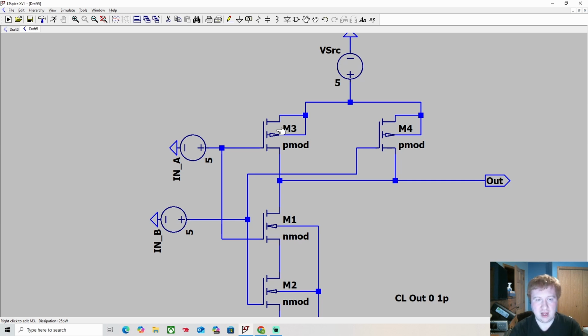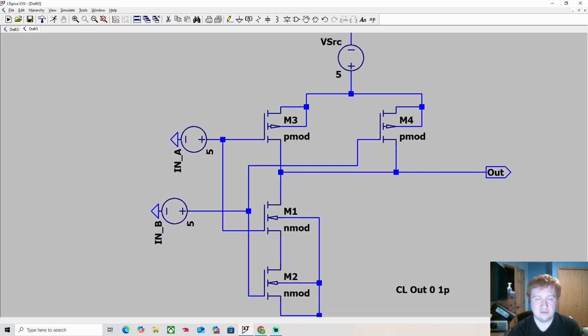And if there is no voltage on the gate, 0 volts, or if it's less than the source voltage, the MOSFET will conduct. So a positive MOSFET in the high side configuration will act as a normally closed switch if there's no voltage supplied on the gate of the MOSFET. And if there is voltage, it will open the switch.